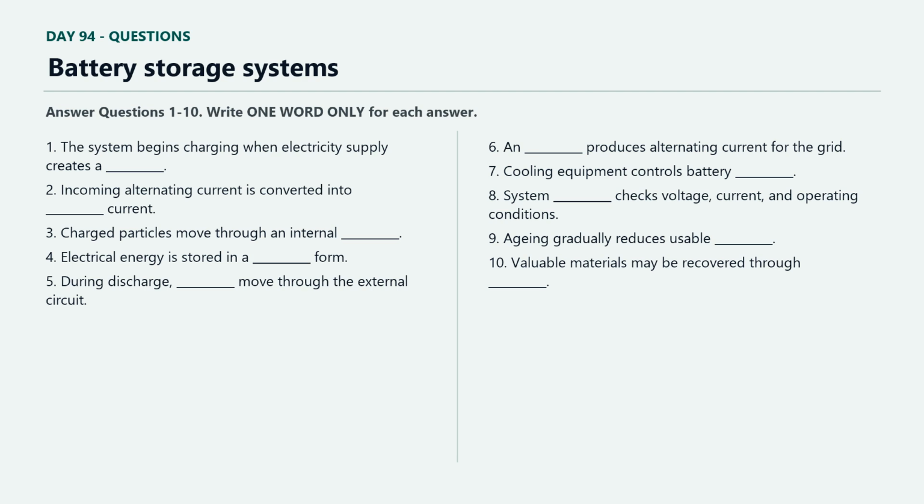Energy is lost in the cells, cables, conversion equipment, and cooling system during a complete cycle. Round-trip efficiency compares the energy returned with the energy used to charge the plant. It should be measured under stated conditions because losses change with power level, weather, and auxiliary equipment.